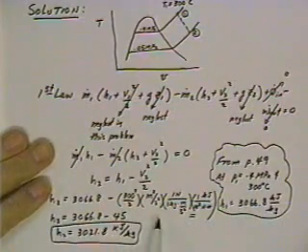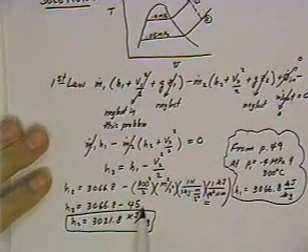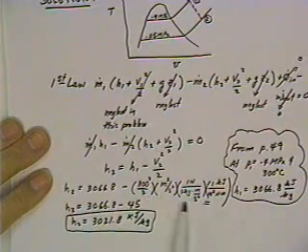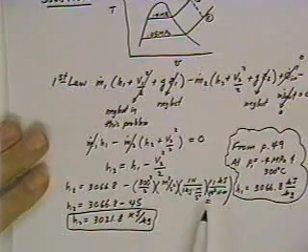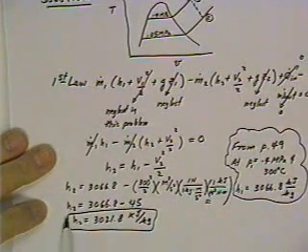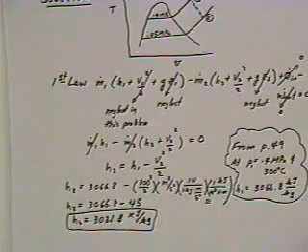Okay, so the kinetic energy term then turns out to be about 45, as you might expect, not really highly significant compared to the initial enthalpy. So when you take the difference here, H2 then turns out to be 3021.8 kilojoules per kilogram. And so this is an example of using the steam tables to find the information that you need.